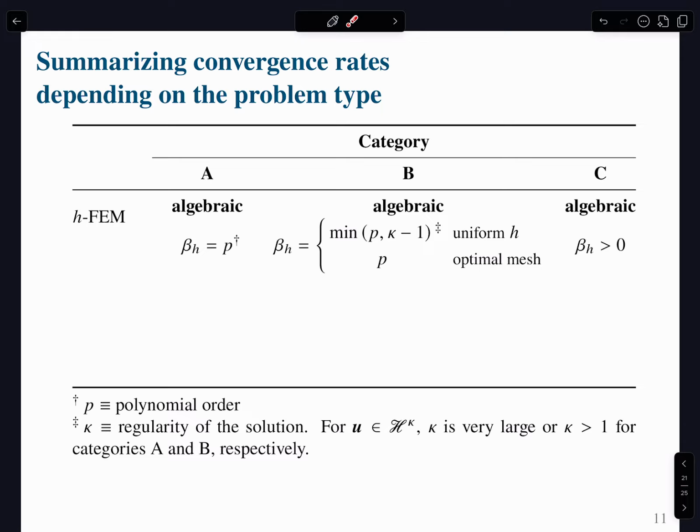Yeah? How can you calculate k? Sorry? How can we calculate k? Well, there are some problems for which you can obtain an exact solution. For instance, there is a whole body of research on linear elastic fracture mechanics, dealing with cracks. You can obtain exact solutions using some advanced approaches, like Airy stress functions.